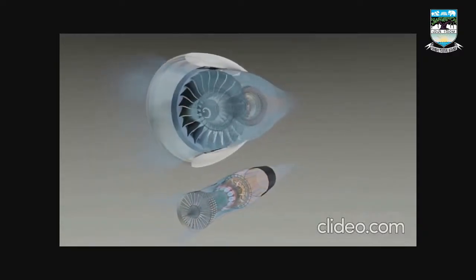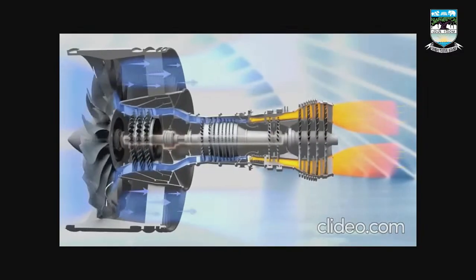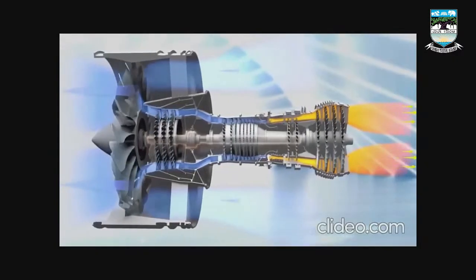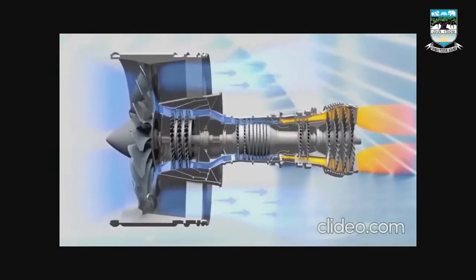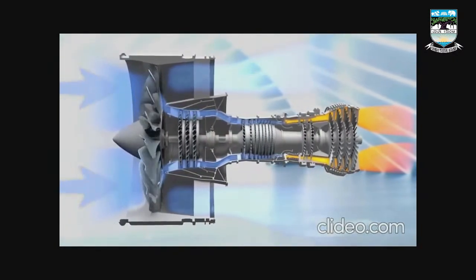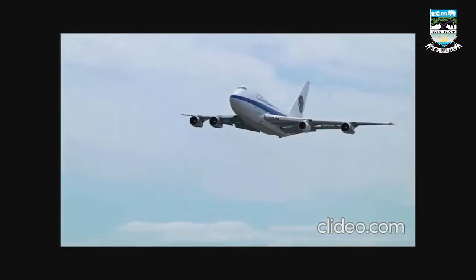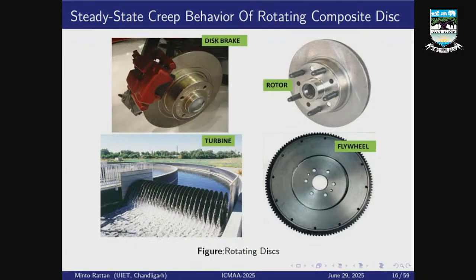Experimental studies have demonstrated that the steady state creep rate in aluminium or its alloys may be reduced by several orders of magnitude when it is reinforced with ceramic particles or whiskers like silicon carbide. Any research work on composites should therefore attempt to analyze creep in structural components like a rotating disc made of lightweight aluminium ceramic composite, so as to develop more reliable design codes for real-life applications.